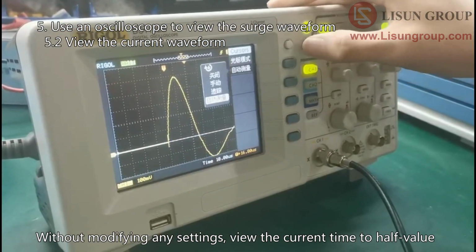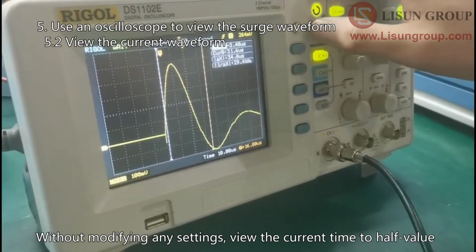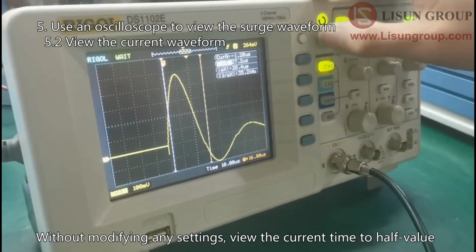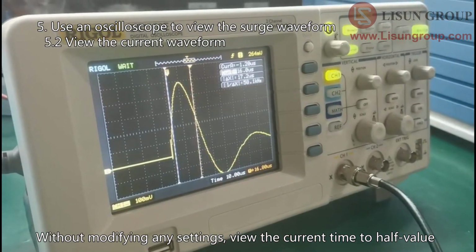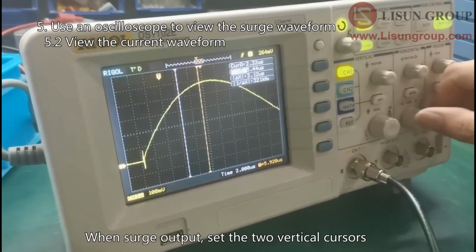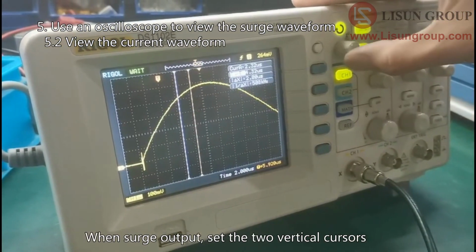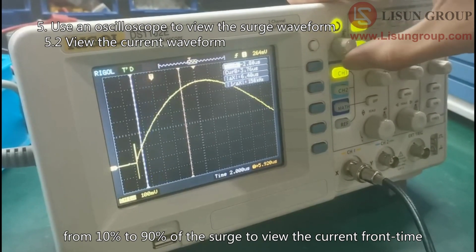Without modifying any settings, view the current time to half value. Set the horizontal axis to 2 microseconds. When surge output, set the two vertical cursors from 10% to 90% of the surge to view the current front time.